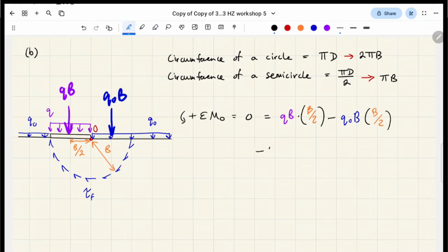And we do the same thing as before. We're going to subtract off the shear strength multiplied by the arc length, which is pi b, multiplied by the lever arm, which is b. Okay, I'm going to cancel a bunch of stuff. And we also know that the shear strength was Cu. Okay, do the exact same thing. We're going to rearrange for Q. Oh, sorry. You know what? I'm going to do an extra step.